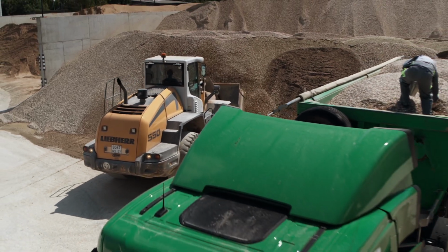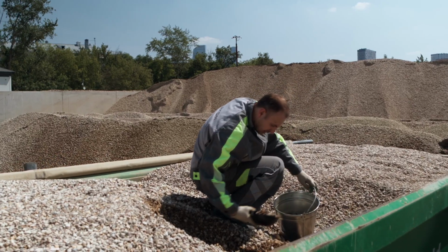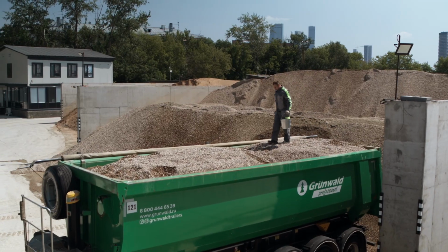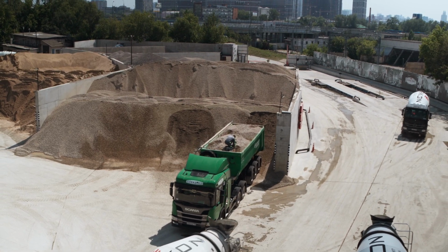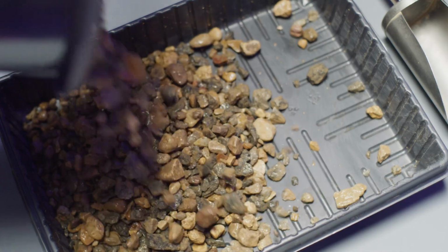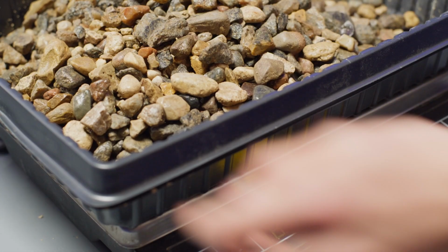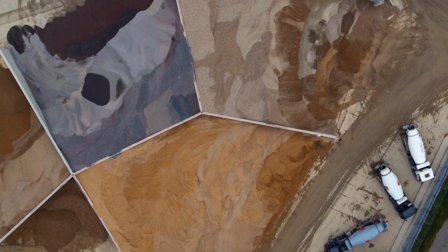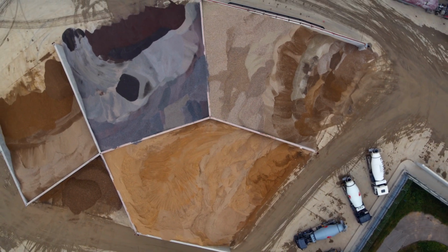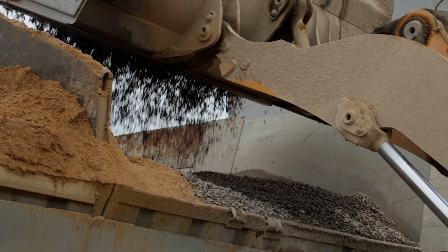After the sand is examined from all sides, the laboratory technicians take up crushed stone or gravel. It depends on what will be used as a large aggregate in the mortar at the moment. To begin with, a sample of the material is tested like sand for the amount of harmful impurities. Then comes the strength test. After all, crushed stone is the skeleton of concrete, and the skeleton must be strong.